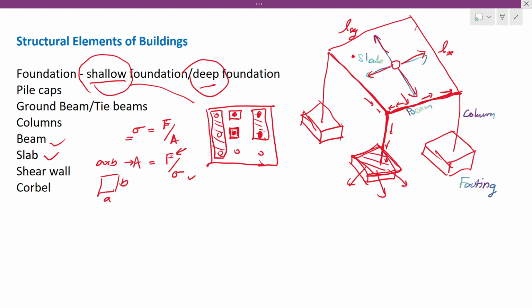When you have a strip footing also, you have a total column load, and from that you can calculate this area. So this is the concept. I'm not going to discuss it in detail; I'm telling you the concept, how it comes or how it varies. As I explained previously, when we have a smaller bearing capacity, the area of the footing will be increased, because when this figure gets smaller, the area will increase. Therefore, you have to have a higher area for a lower bearing capacity. Okay, that's all about the shallow foundations.